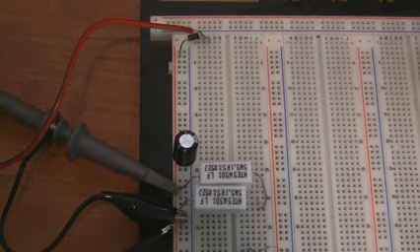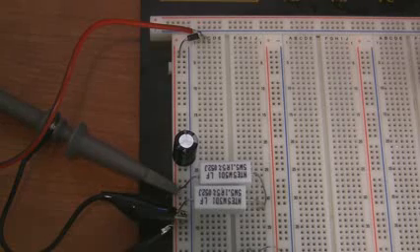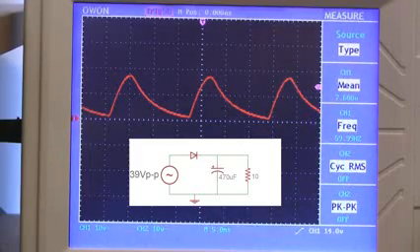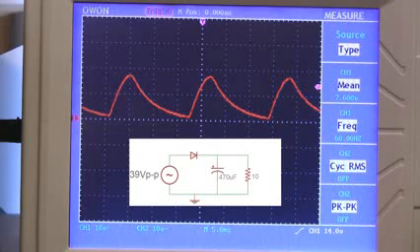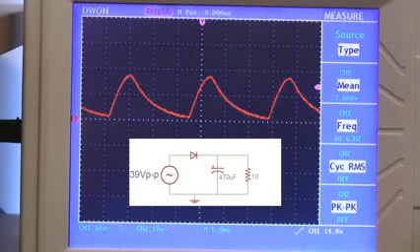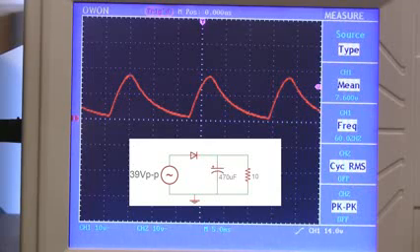Okay, let's turn it up a notch. With a 10 ohm load, this circuit should draw a lot more current. Well, that sucks. Now we're back to the situation where the voltage is sagging in every cycle. The average voltage is 8 volts, so we're only drawing about 0.8 amps, and the magnitude of the voltage ripple is just huge.